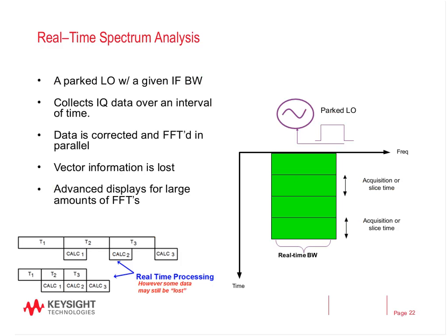So you can park the spectrum analyzer, let's say at 18 gigahertz, your center frequency, or 2 gigahertz, and you could digitize the full 500 megahertz bandwidth. Okay. In this case, when you capture IQ data, you're still going to have missing information. So during the capture phase, it's continuous, but when you have to offload that data and store it, you basically stop capturing and you have a large amount of lost information. Okay, and so you still have a problem trying to find those elusive spurs.